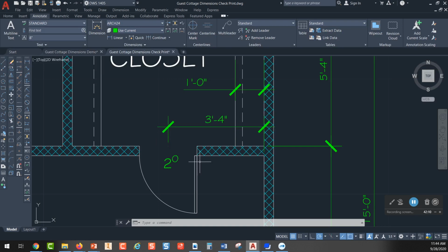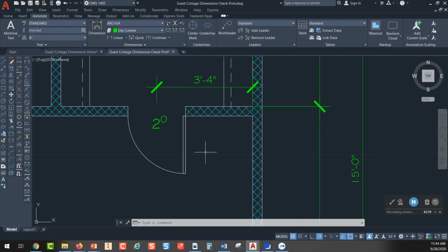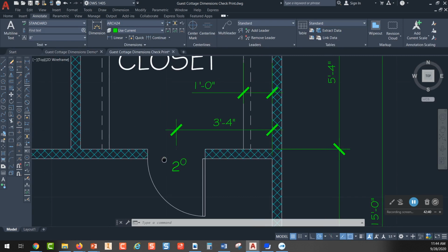Then we say there's a 2.0 door. So they're going to put a rough opening here. So instead of framing that 24 inches, because it's 2 feet wide, they're going to frame it 26.5 inches wide. And then the door is actually going to come in with a door jamb around it, and they're going to put it in. That's why it's got to be wider for one thing. But we're also telling them that when you hang the door, we want the door to swing outward. We want the hinge jamb to be over here, and we want the strike jamb to be on this side.